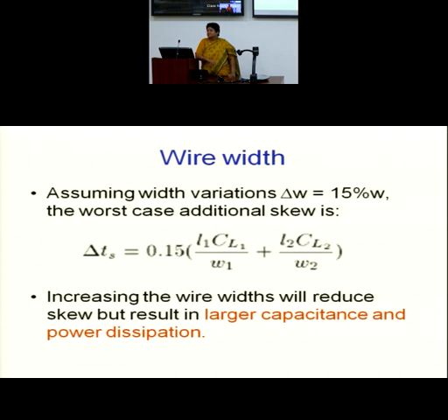If there is, let's say, crosstalk between wire 1 and wire 2, will that affect the design? I am not considering that right now. Crosstalk comes in terms of noise. Crosstalk is a form of noise, and yes, it is one of the issues. Normally crosstalk is resolved by separating the wires, because the moment wires are separated enough, the crosstalk reduces drastically. Or between two wires, we place a ground rail so that mutual coupling gets reduced. It gets eliminated. So there are techniques for reducing crosstalk.